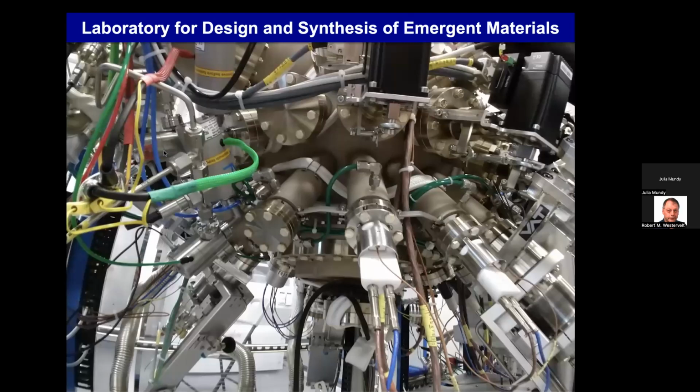Okay. Yeah. So this is just a unit. Each of these, as I mentioned, is these cans, these thermal evaporators that have each of the elements in them. And so we have wires going in them. So it's resistive heating, the same way a toaster oven works. So we're just very finely controlling the heating of these cells. And then we have thermocouples and what have you that we're monitoring. And then, as I mentioned, the row above is the shutters. And then this is also kind of cool, the oxygen. We can control the oxygen in the chamber very precisely as well. So that's it.